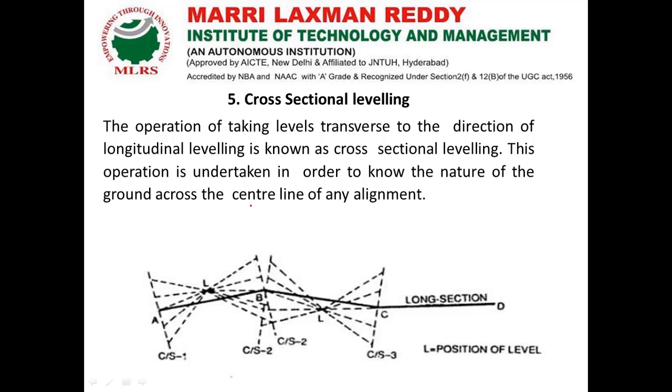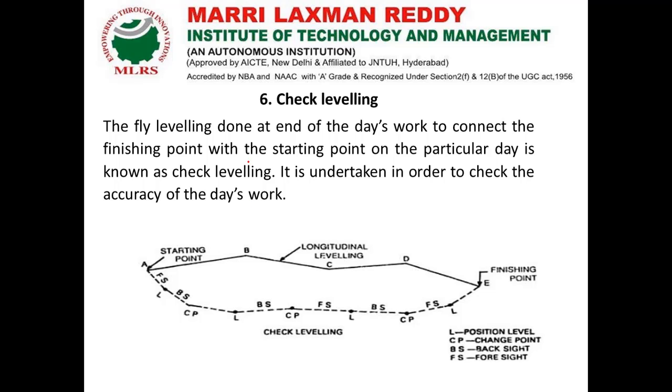Next, check leveling. Once we have finished the entire work, we have to check whether our process is correct or not. In order to ensure our work accuracy, we have to do fly leveling from the starting point to the end point, or end point to starting point, till the benchmark wherever we have one. This process is called check leveling.